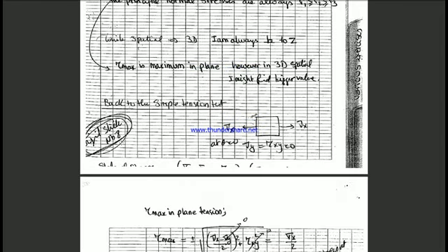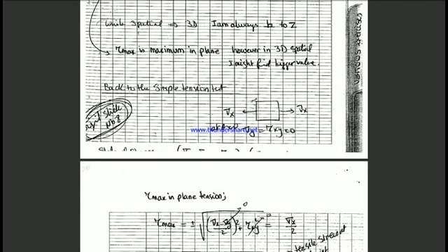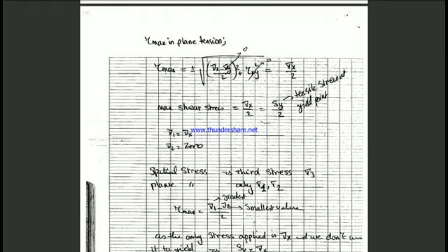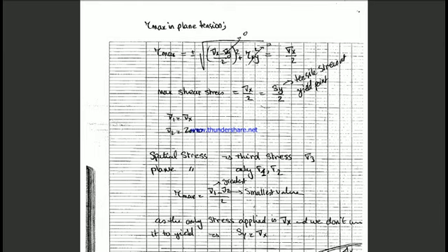So let's go back to the simple tension test. If we have a tension, we have sigma x only. We don't have sigma y in this case because it's a simple tension test, and tau xy is equal to 0. So with sigma y equal to 0 and tau xy equal to 0, those equations literally give tau maximum equal to sigma x over 2.